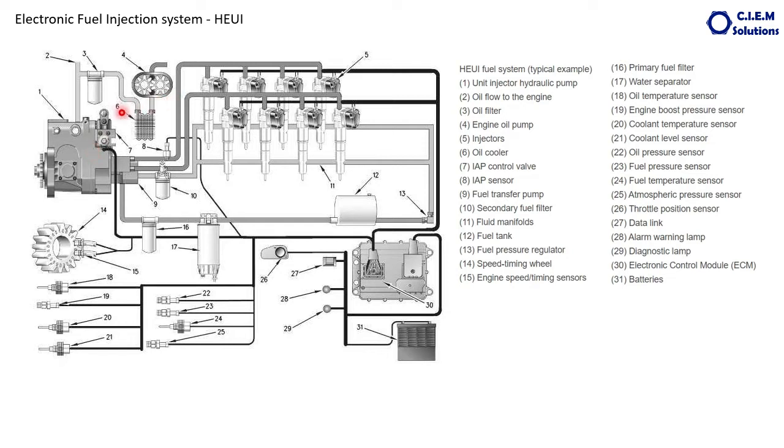At the inlet side, the oil pressure is approximately 4 to 5 bar, and when it comes out of the pump, the oil pressure, shown by this dark line, is higher. This light gray line is the fuel pressure. The oil pressure will be from 100 bar to 250 bar depending on the requirement of the system. How the pressure varies, I will tell you. This component is called the high pressure oil pump, which develops the injection pressure from 100 to 250 bar.